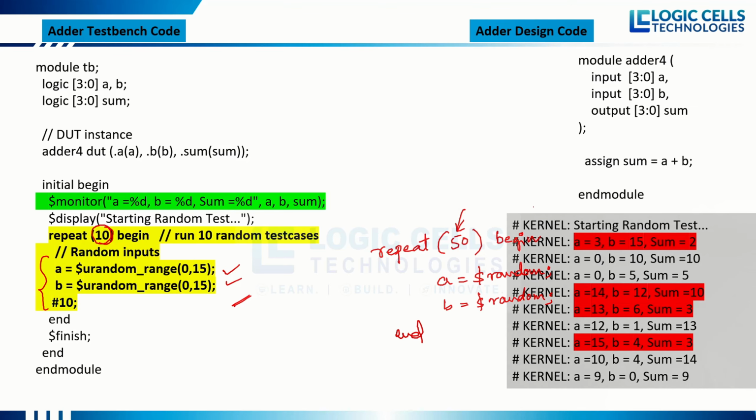In this case also, because of this issue, we have seen this already yesterday, right? This is the issue. For adding 3 down to 0 A and 3 down to 0 B, we need to have 4 down to 0 sum, correct? But the designer has designed with 3 down to 0. This is a bug, an issue in the design. It may work for small values. If you take 4 plus 2 as 6, it may work. Why? Because 6 will be represented as 0110, and 3 down to 0 supports it.